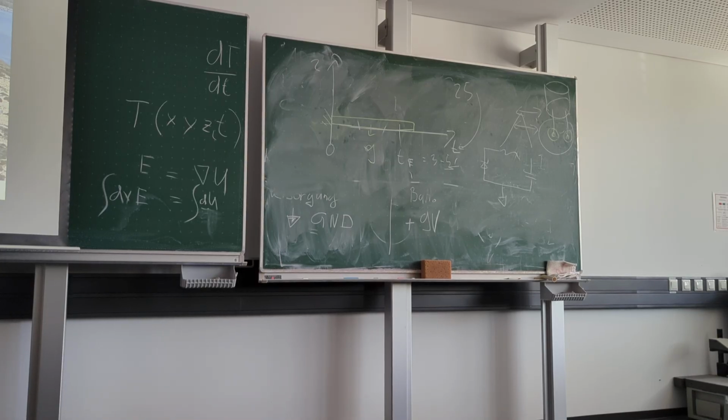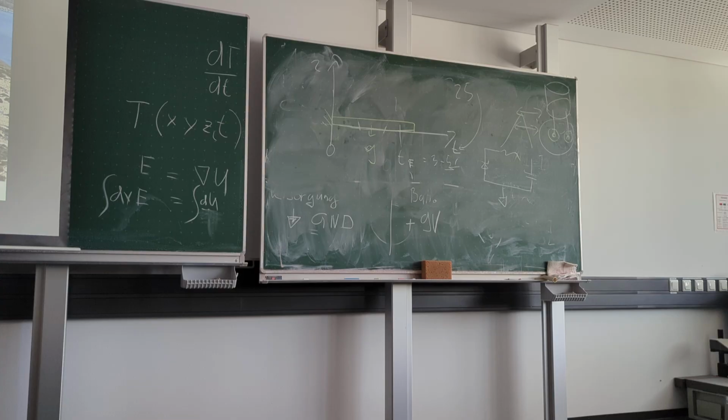How to do this? We go to solid mechanics. You know, you always find things here with a right mouse click. Usually we do boundary conditions, and edge conditions we did last time, and this time we do a volume condition. So in the first section, there is something called volume forces, body load.